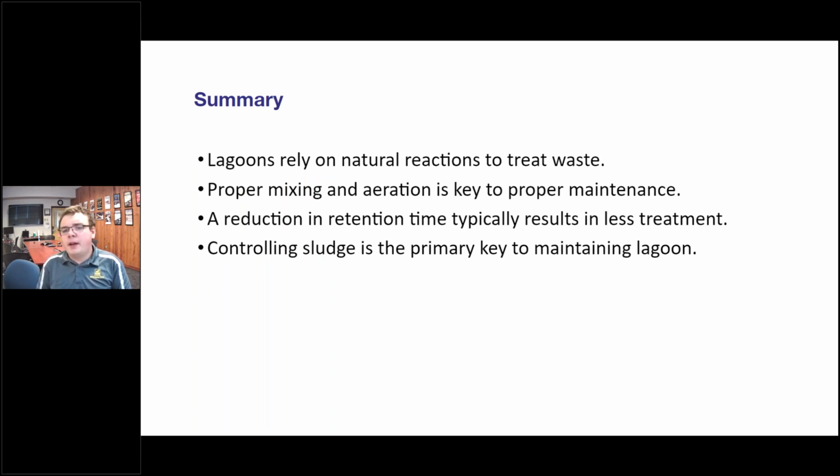So just to wrap up a bit here, we've got just 4 main points to go off of. Lagoons are relying on natural reactions to treat waste. You're not typically putting large chemical amounts into your lagoon system. Proper mixing and aeration is a big key to keeping your contact time up, keeping your particles moving, and just keeping everything in balance.